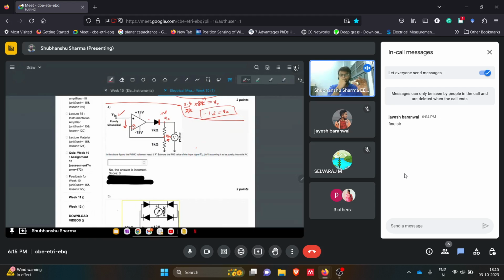One thing to keep in mind is that if the diode is on, then this feedback will work. If the diode is off, then this feedback will not work. The reasoning is that only when this diode is on will the op amp get a feedback, and only then is this thing attached to the feedback and given back to the op amp.